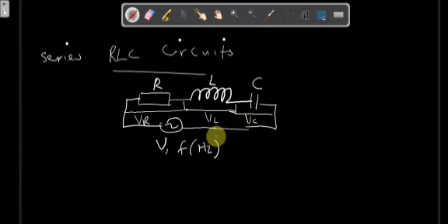Now, for a normal DC circuit, you can just add the voltages together because they are in series. But because they have both magnitude and direction, you cannot add them together like that. Before I go to the formula, we can use a phasor diagram to represent this.